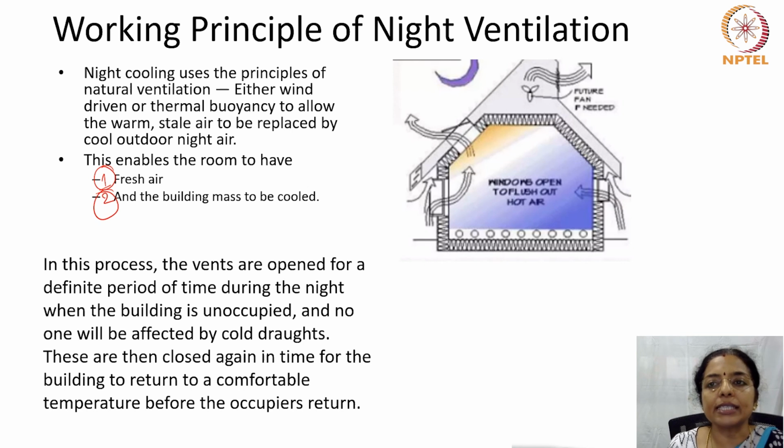In this process, the vents are opened for a definite period of time during night when the building is not occupied and no one will be affected by the cold drafts. Then these are closed again in time for the building to return to a comfortable temperature before the occupiers return to the building.